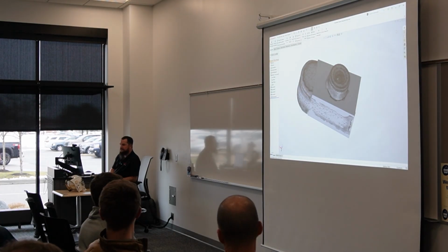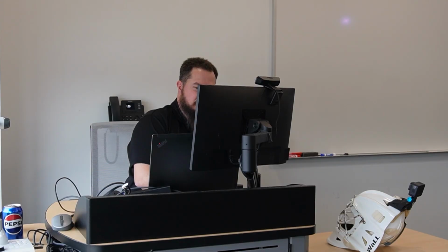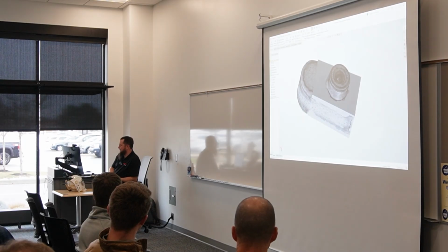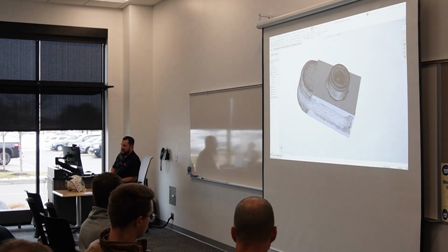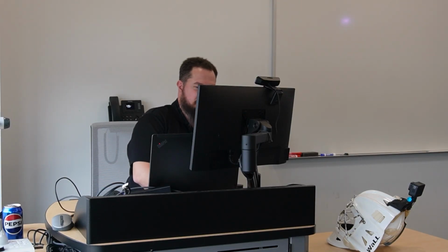Is there a benefit to saving it as OBJ as opposed to other file formats? That is a great question. For the purpose of this, OBJ, step files, all that fun stuff, they're pretty much interchangeable. When it comes to saving out in other formats, given the choice, I generally save as a 3MF. If you're not familiar with 3D printing and 3MF files, that's something that's been developed specifically for 3D printing. So I try to defer to that in most cases, but for reverse engineering, it's whatever format you prefer. Good question.